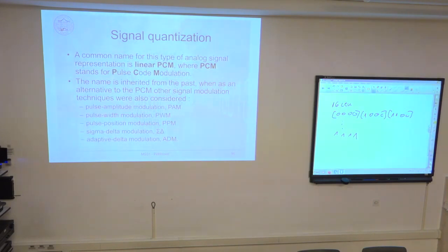So at the output of this sigma delta modulator, you will have a sequence of only 1 bit, 1 0, 1 0. And this sequence of 1-bit values is digitally processed with a digital filter to create a 16-bit value represented by this sequence, highly frequently changing 1 0 1.